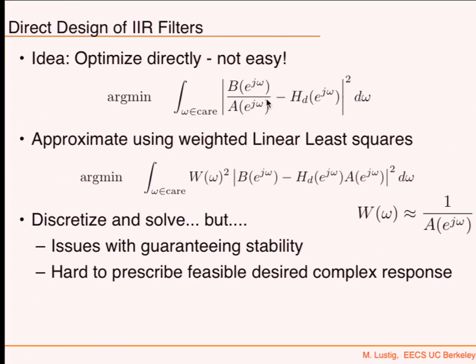Okay, so now we're going to talk about these linear difference equations, and we're going to look at effectively what is a magnitude response and what is a phase response of these systems, and try to get an intuition and understanding of how these relate to the Z-transform. If you have a particular Z-transform, what will then be the magnitude response and the frequency response of these systems?